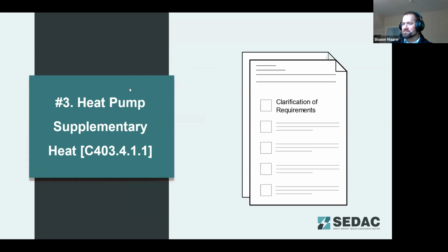Our first question, which systems are required to have fault detection and diagnostics in a 200,000 square foot facility according to the 2021 IECC? There's multiple answers here that are correct. So pick all that you think are correct. Do the economizers need it? The central boiler and chiller plants, individual VAV boxes and zone controls, individual RTUs serving smaller areas of that building. And then number two, which is not a consequence of oversizing HVAC equipment: higher capital costs for equipment and materials, poor humidity control, excessive wear from extended operating hours, or excessive wear from rapid start-stop cycles.